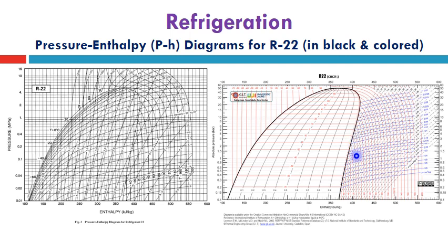Also the constant temperature lines in red are shown here after going out from this vapor saturation line, where it was horizontal inside the wet region and almost vertical in the subcooled region due to the constant Cp of the refrigerant in this area.